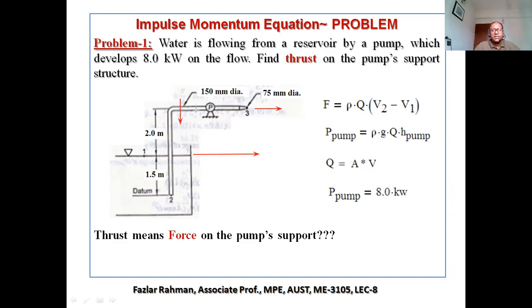Even though we are getting the same fluid, same Q, right over here the velocity would not be the same, because the area of the nozzle is smaller, right? So over here, velocity will be high, and before the pump, velocity will be low.